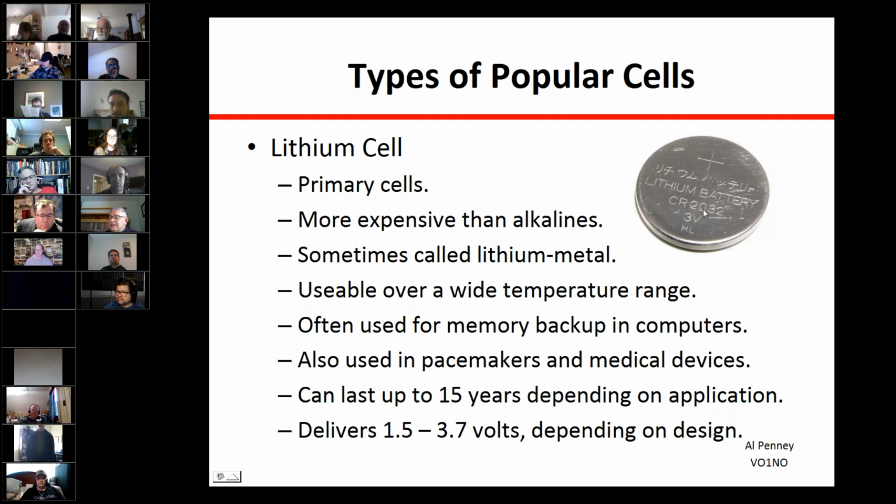Now, one thing about these in a radio, they'll have the terminal wires spot welded to them. You can't solder because it's difficult to solder to the case of the thing, and you'd also overheat the battery and cause it to, well, I won't say explode, but certainly split. So if you are going to attach a terminal to these when you're replacing it, you've got to go to a battery place that can do some spot welding and just spot weld the tab on there.